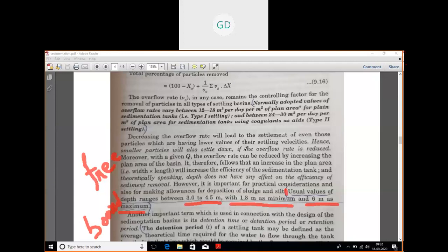That is known as your freeboard, and you need to add that freeboard while calculating the depth of the tank. You will see while we calculate the numerical that they have added it. So you have written up to here.